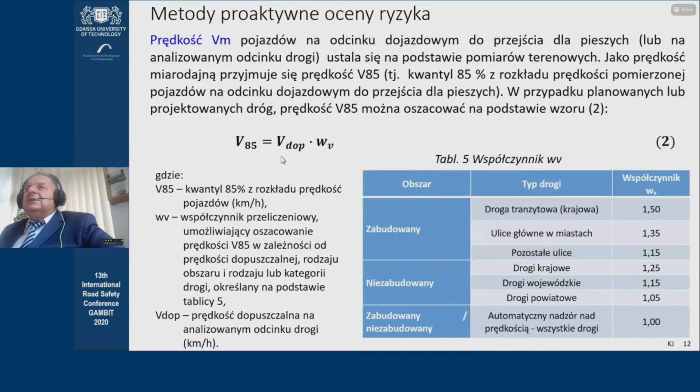And we have a similar classification for sections of roads. Speed is the next factor. We use the reference speed, which is the 85th percentile, which is the speed limit times, well, because obviously if we cannot measure it, then at least we have to estimate this. And so we will use a study we conducted before in built-up and non-built-up areas, whether there is a speed camera or not.